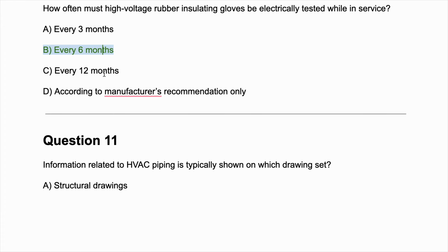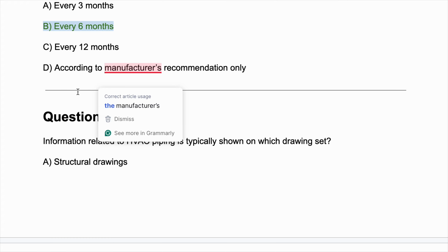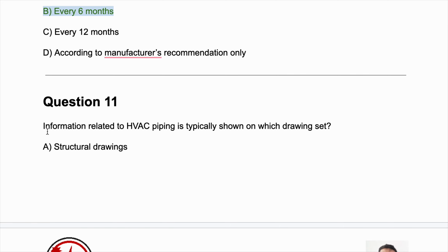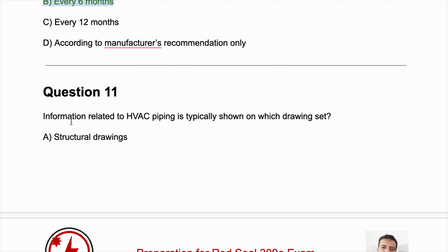I mean that before the first usage of these insulating gloves, it can be just 12 months in the warehouse or in the store, not more than 12 months. If it has remained unsold in the store for 12 months, it needs another insulation test.